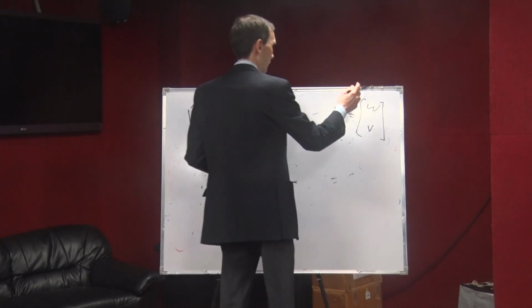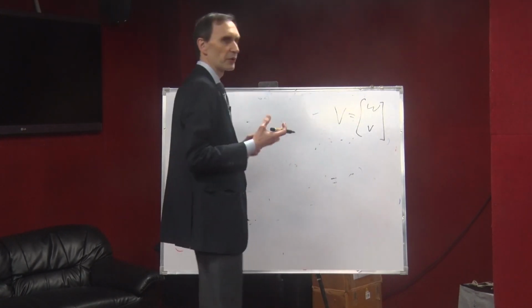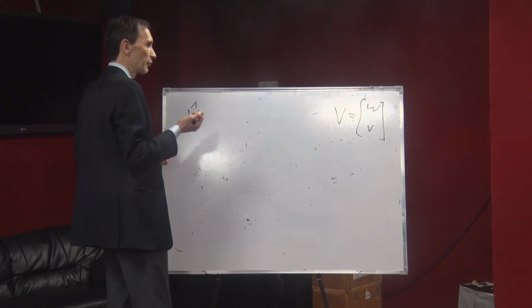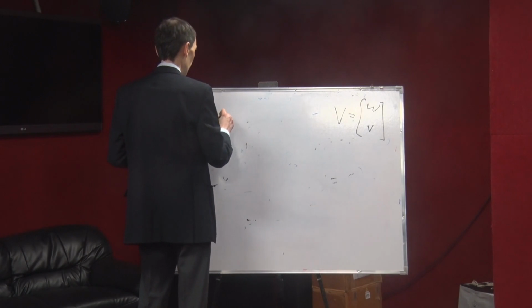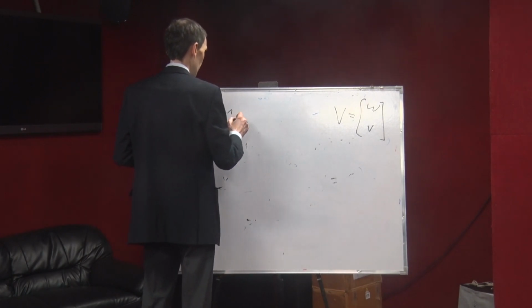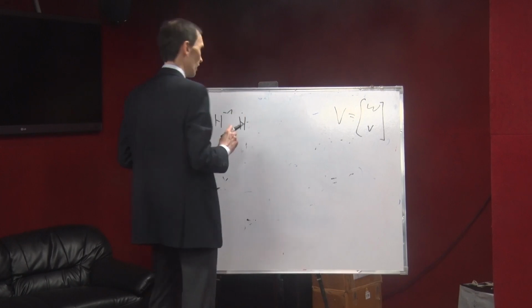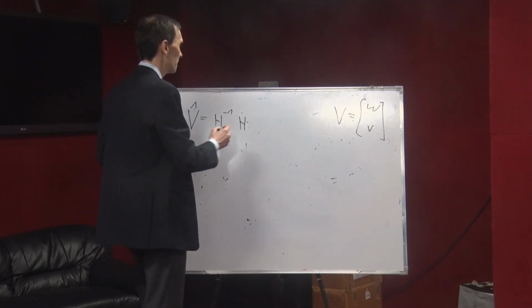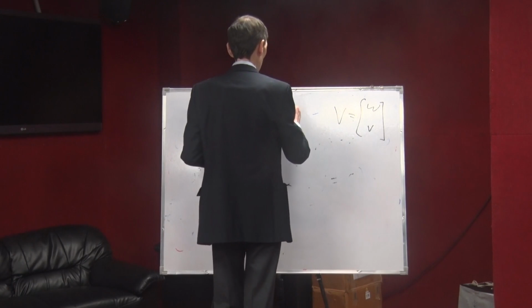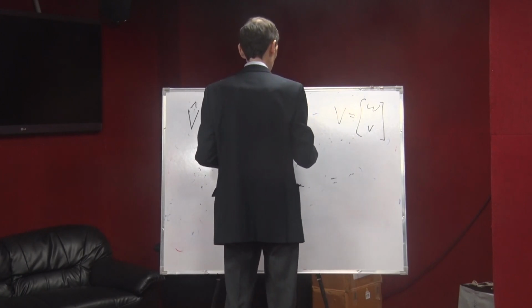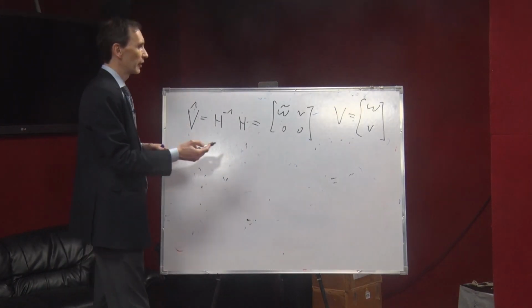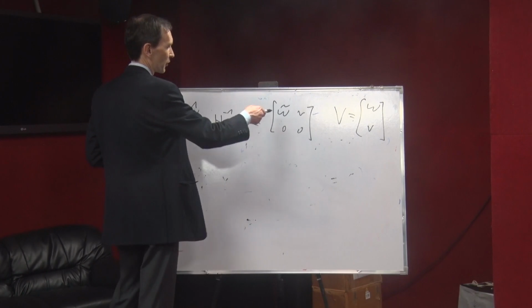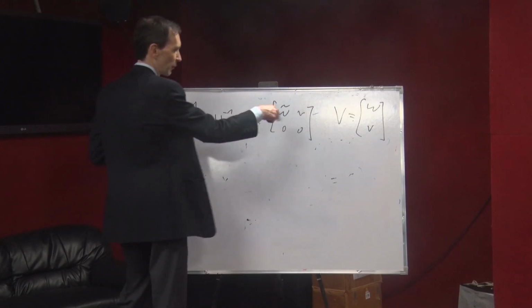And we had the v on top just to say this is in body-fixed coordinates. And how did we define it? We defined it by taking the inverse of our H matrix times H dot. And then what it gives you is this matrix, omega tilde, little v, 0, 0. And then we said we can uniquely identify the 6-vector out of this 4 times 4 matrix.